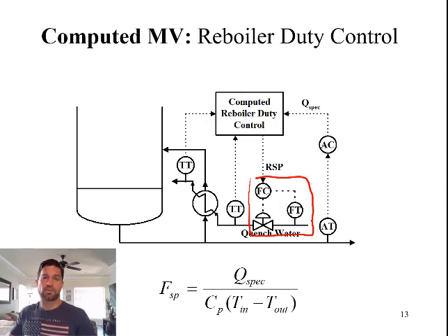If the temperature of the quench water coming in changes, the temperature coming out is also going to change, and we know that the amount of heating is going to be based on the delta T. We can't know what the temperature coming out is going to be, or it's not necessarily dependent on the temperature coming in. So in order to get better control of the heating to the system, we need a measurement of both the temperatures.